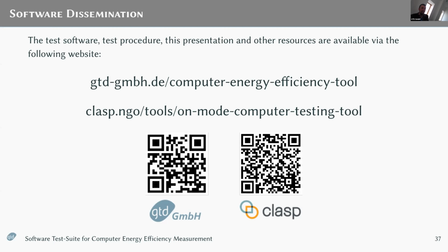Interesting question. Yeah. As I showed when we looked at the result viewer, you get the statistical numbers for the performance results. So you get with every result the standard error, and usually the tool is set up to rerun the worklets so that the standard error becomes lower than a certain threshold, which is configurable.